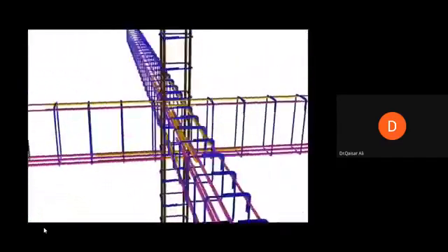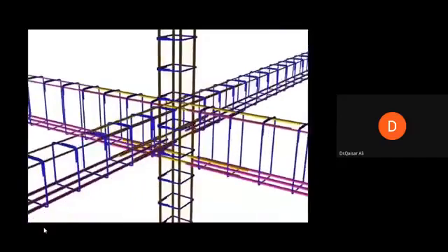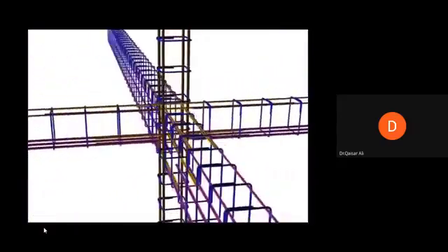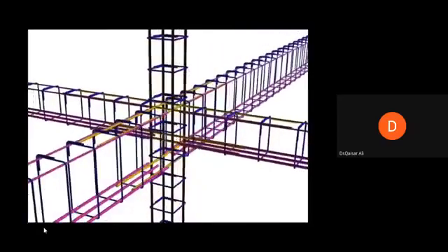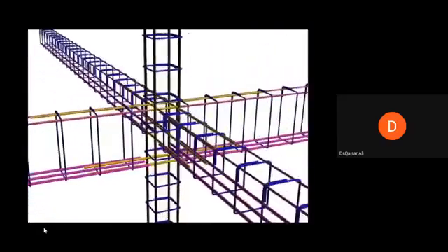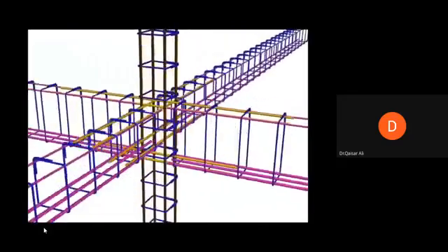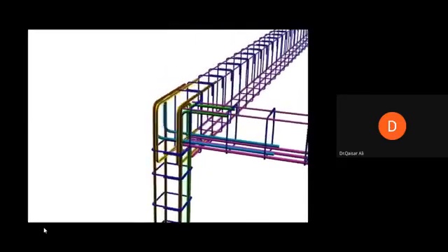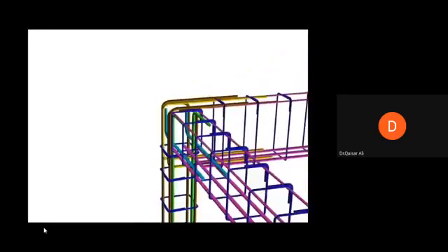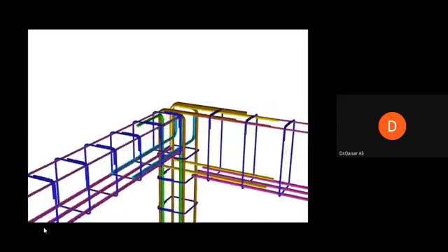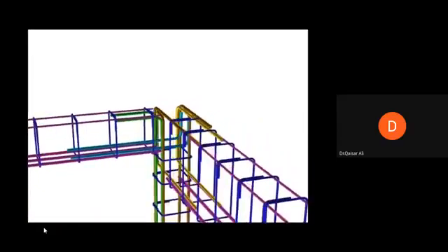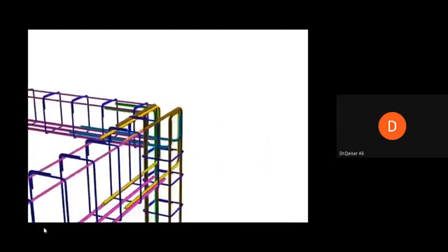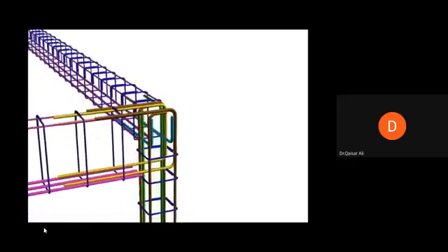This is a central joint where both the beams running in both directions are going through the column. This is a top floor corner. The column reinforcement also terminates now. The column reinforcing bars terminate and bend in the beam, and the beam reinforcement terminates inside the column.